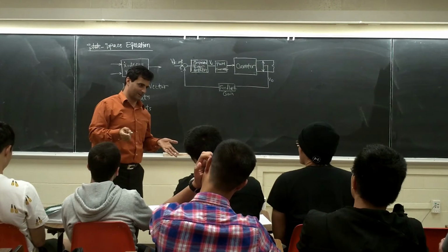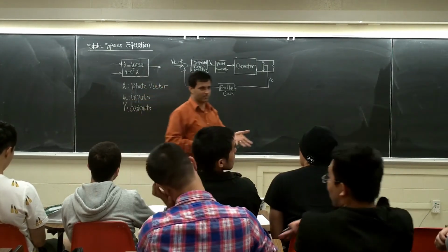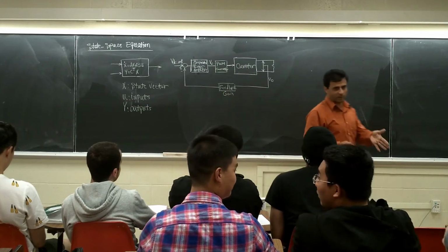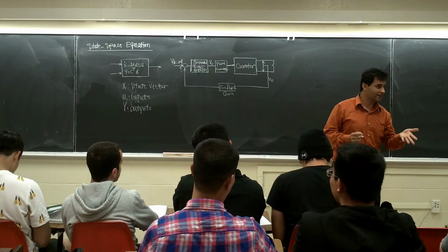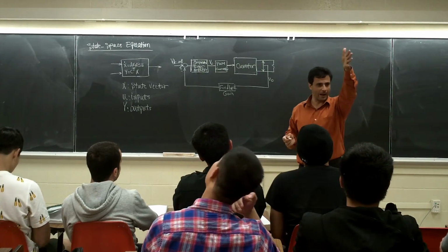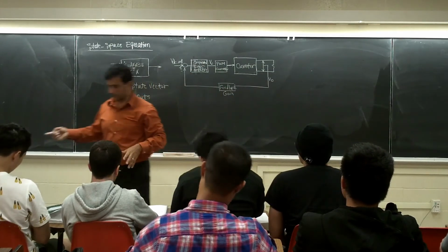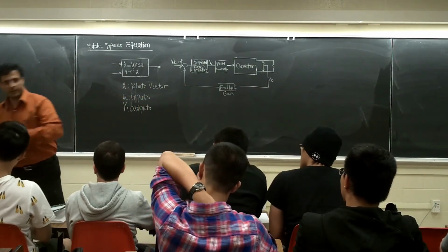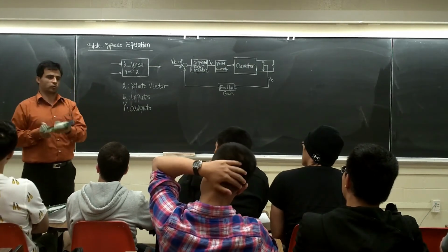This is a bad design. You know what I'm saying? It's the exact control system. I'm just trying to give you this example so you can feel it better. What's bad about overshoot? You're going to pass your reference. Sometimes it's okay, sometimes it's not. You pass the reference, and something bad is going to happen. For example, if you have a current for this module, this IDIQ, I don't know, let me see this one. How much is the current rating? This is a 100 amp module, right?